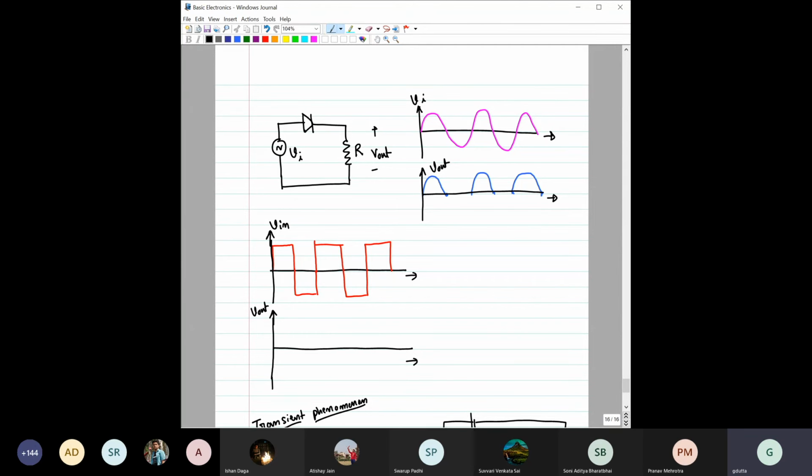I am saying design, only one parameter we have discussed, that is the doping concentration. Other than that, the structure and all these things also determine what the breakdown voltage would be. But one of the primary things is the doping concentration.